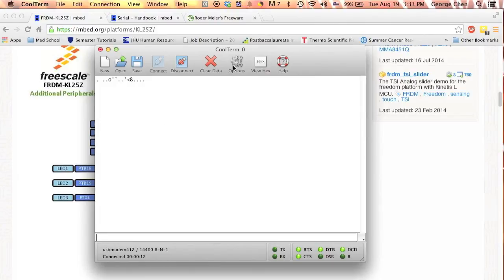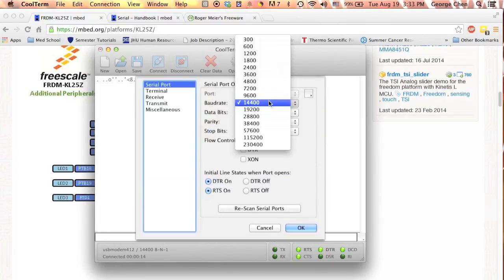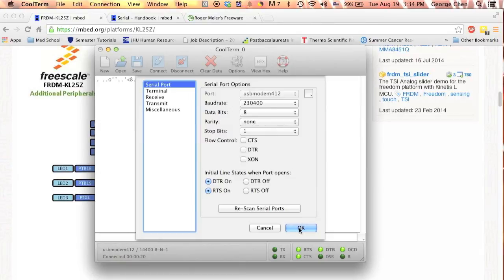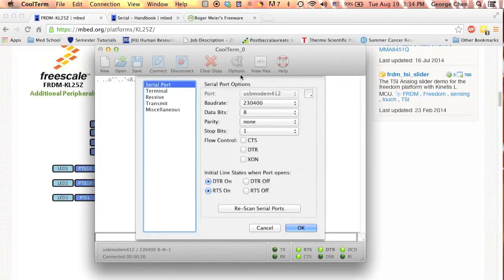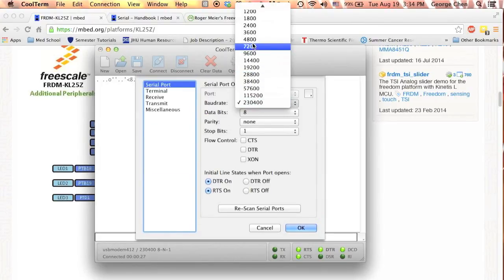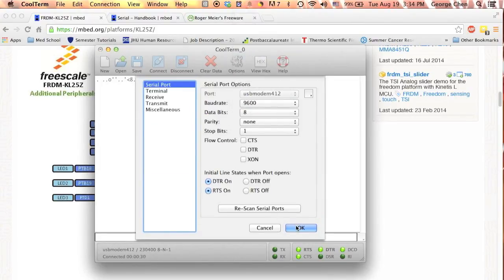So the idea behind this is that you have to ensure that your baud rate is the same baud rate as what is being transmitted. Again, if you set it to the fastest baud rate, it's going to be a bunch of garble as well. So I'm going to hit reset again and look, a bunch of garble, nothing. So with that, you can set and change the baud rate options on your microcontroller by using this command called .baud.